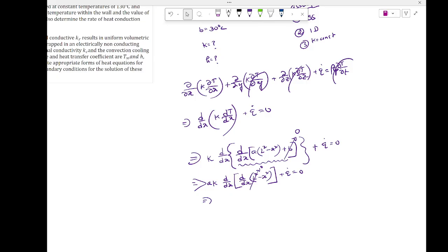If you can somehow find the conduction, conduction is what? You know the equation, right? It requires K value. Once you find the K from here, you can find the conduction, right? Once you know the conduction, it will be convection. Especially if you stick with flux, you don't even have to worry about the area. If you do the flux, then don't worry about the area, right? And this is going to lead you to the value of the H. So yes, you still wind up with your H. So you're doing double derivative.